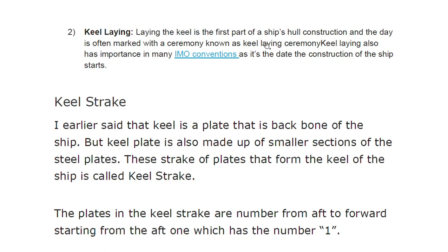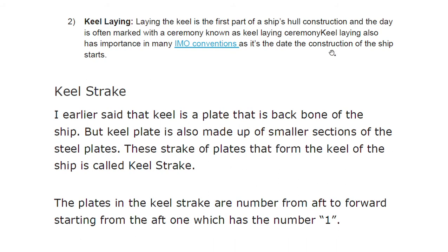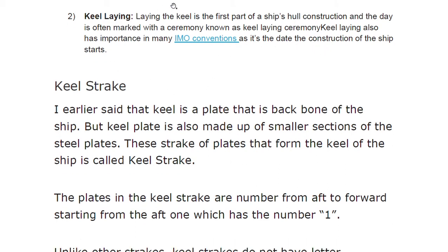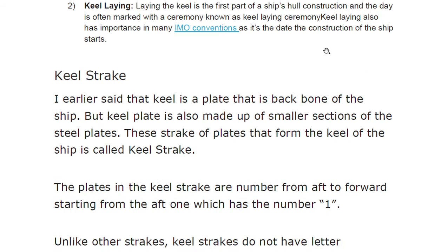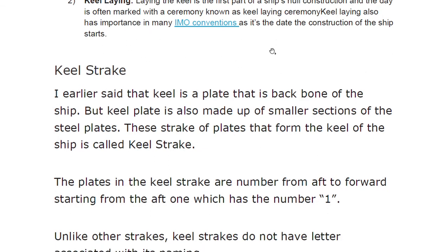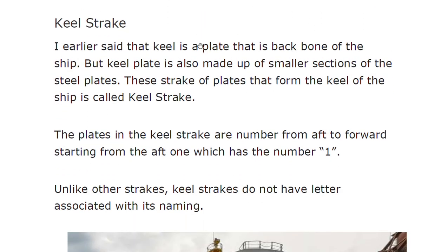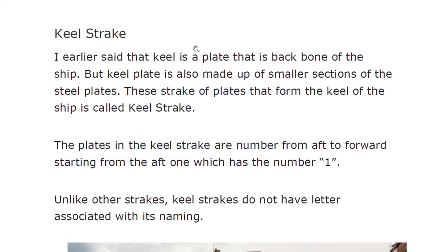Laying the keel is the first part in the hull construction, and the day is often marked as a ceremony known as the keel laying ceremony. Keel laying also has importance in IMO convention, and it is the date the construction of the ship starts. Okay, it is the date which is counted as the ship construction, because you must have imagined all the SOLAS regulations, MARPOL regulations, they are saying ship constructed after so and so. So that is the date. That is the reason why the date comes into picture.